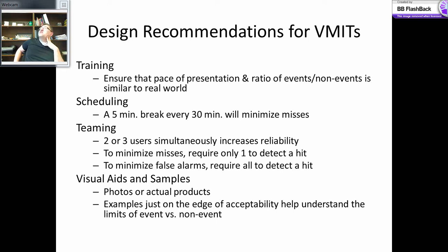So what are the chances that 2 of them are going to fail at the same time? Or 4 of them out of 10 are going to fail at the same time? Now that becomes really unlikely. And so that's what it is. We would call that redundancy. The redundancy aspect says we require more than one simultaneous reception of the signal to decide that the response is necessary. And that really minimizes false alarms.